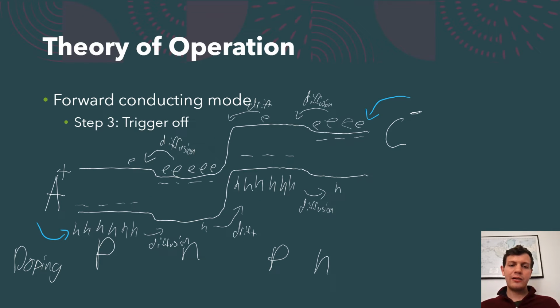Finally, we're in our steady state mode, where we're doing some conduction from anode to cathode, so we can turn our gate voltage off. So it's just going to sit there floating. We could pull it up, but that might reduce the current in the device a little bit, so usually no voltage is being applied. So you could think of it as an open circuit,